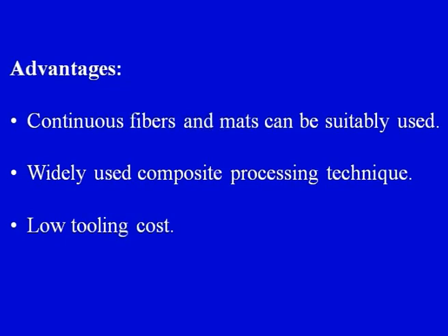Now what are the advantages of the hand layup process? Continuous fibers and mats can be suitably used, it is a widely used composite processing technique, and the tooling costs are very low. The steps are comparatively easy and easy to understand, and the control can be exercised properly in case of a hand layup process. Excess resin anyway we are removing with the help of a consolidation roller.